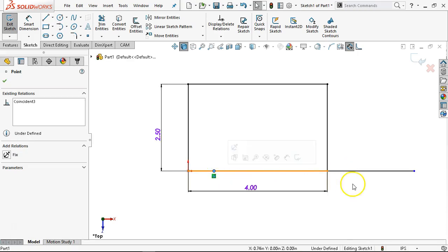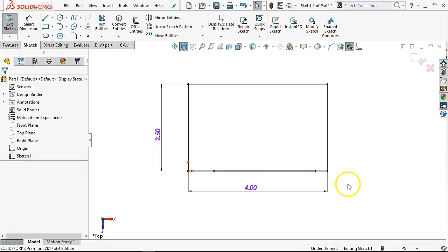What I don't want to do is kind of lose one line under the other. That would cause the sketch to remain underdefined because I have that duplicate entity. It would also cause this to be a contour and region even though my intention wasn't a contour and region. So we're going to pick up contour and region in the features, but it's two conditions that you need to be aware of. All right, and when you see them, because at some point it's a given that you are going to push enough buttons, you are going to have enough geometry that this instance will occur.